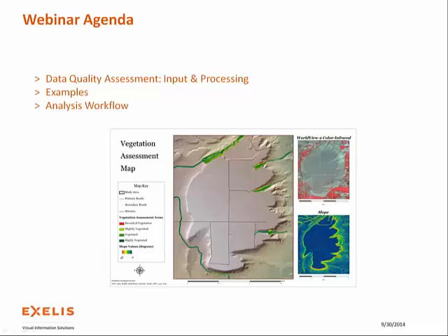And then we're going to perform a deeper dive in analysis workflow to illustrate some of the best practices in action. So for the example today, we're going to look at evaluating some vegetation and look at vegetation filter buffers, which I'll describe in a little bit. They're the zones between basically roads and waterways that are used to filter sediment from production, accidents, other hazards, or anything as it might apply. And before it intersects with a waterway like a stream, an open water body, things like that. And I'll get into more detail of the analysis in just a bit.